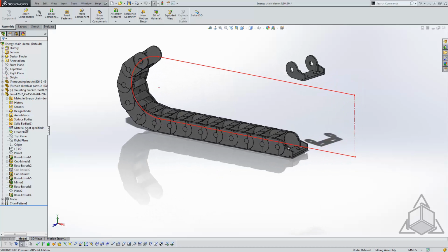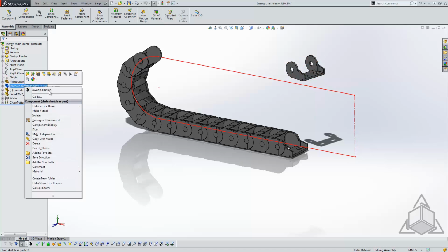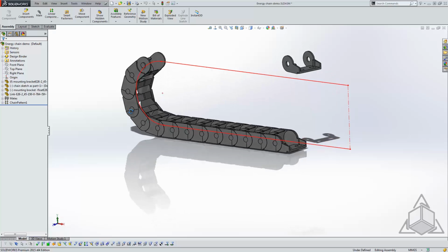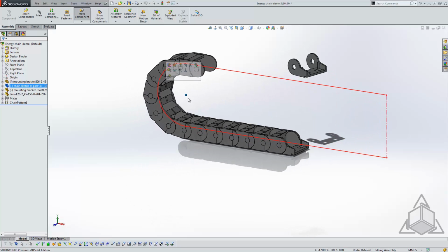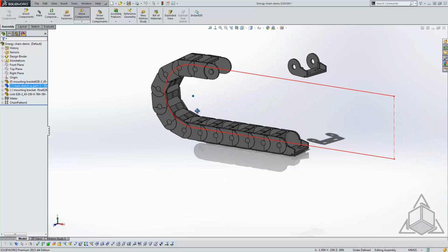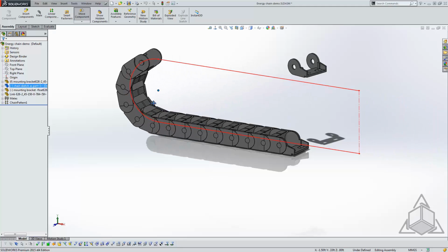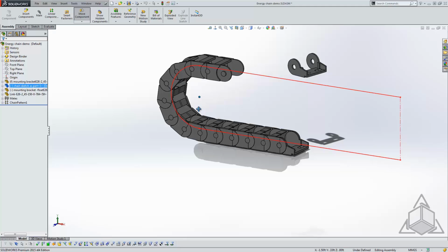And the last technique that I'll show you for using this is actually letting the sketch move. So if I allow this sketch to float instead of just being fixed here, I've allowed this to move just kind of in plane. And what happens is, if we move this sketch now, we see that this whole thing kind of slides along its path. All right, pretty cool. And again, it solves very, very quickly.